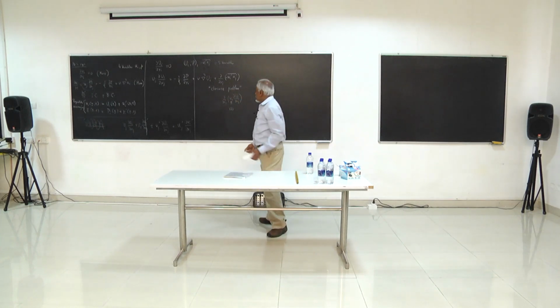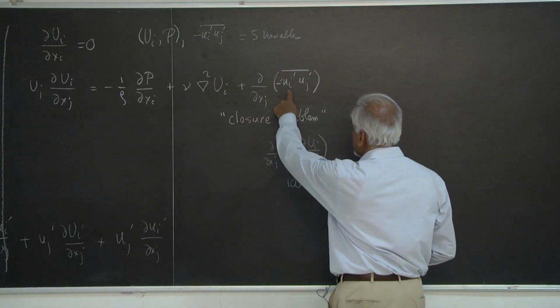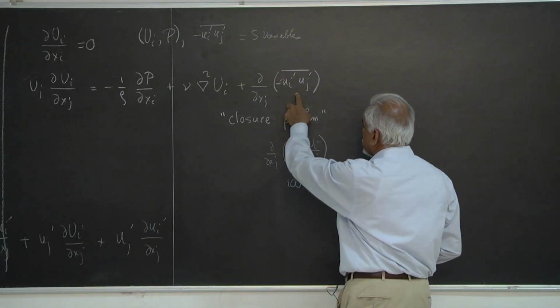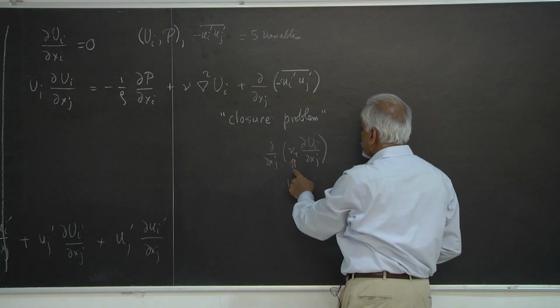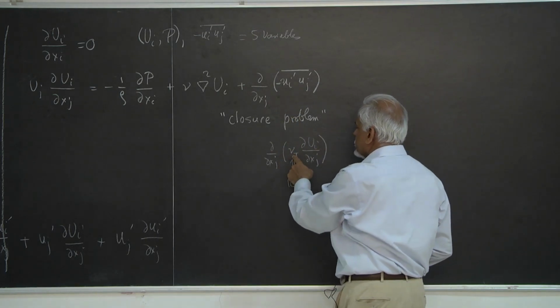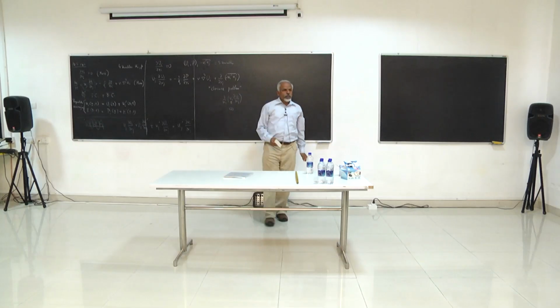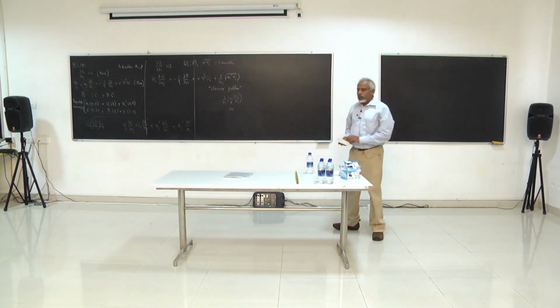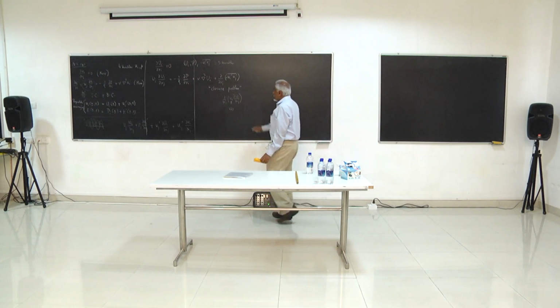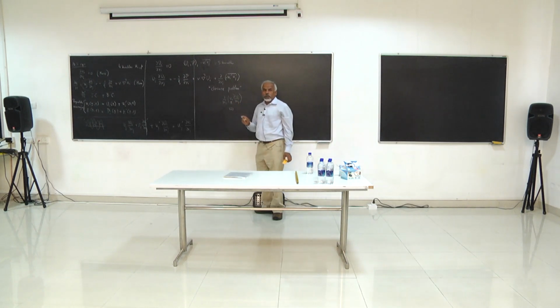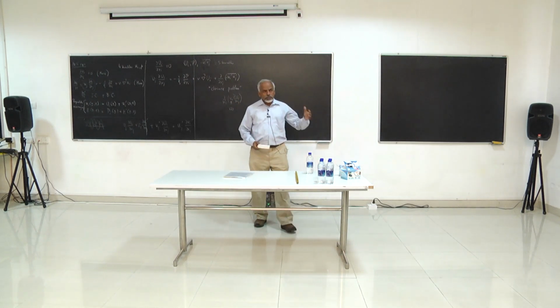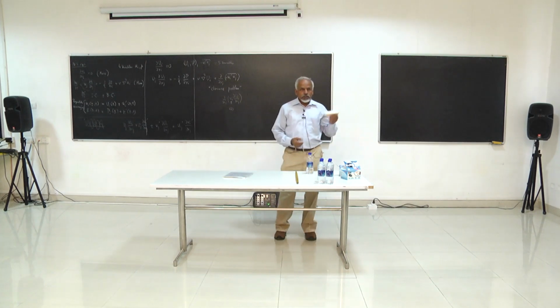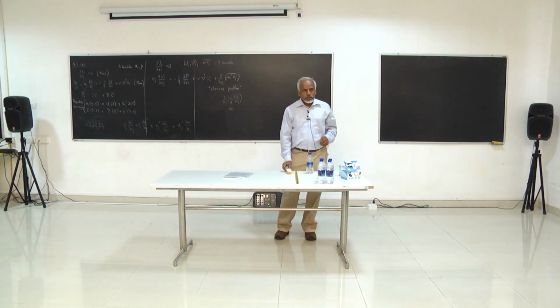because it's not always the case that something like this works. This is something you can measure. Sometimes nu t may go negative, sometimes positive, and sometimes small, sometimes large, etc. And even an average value depends on the flow. If you have pipe flow, it is one thing. If you have atmosphere, it is another. If you have something else, it is another.